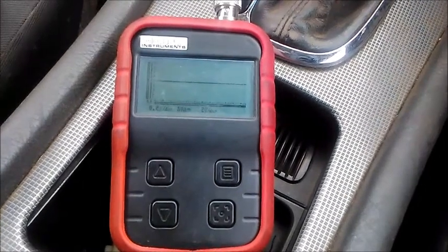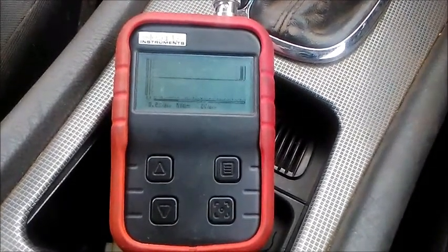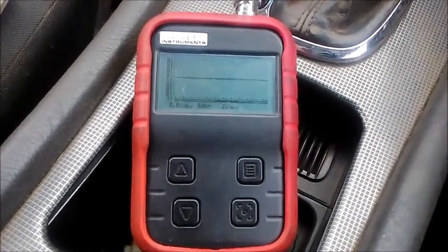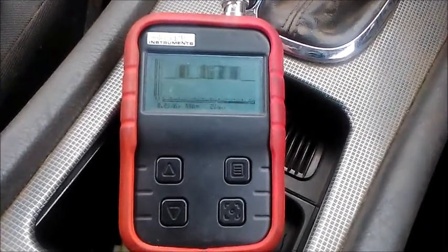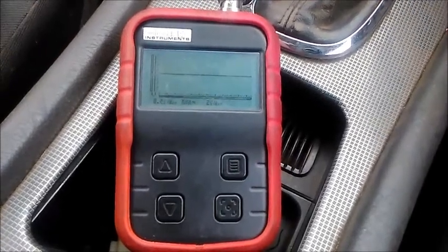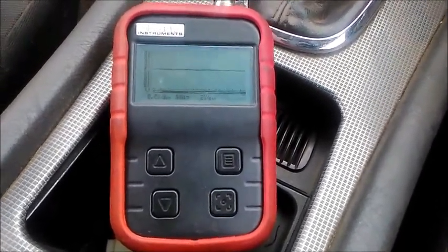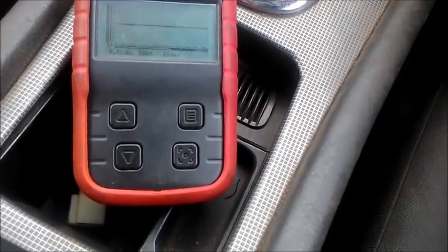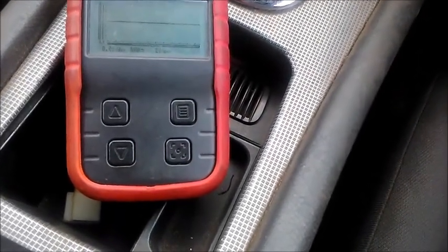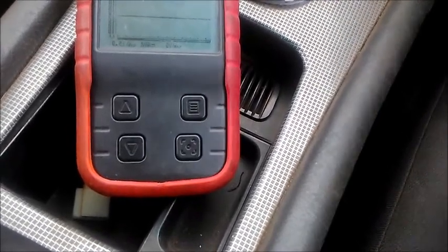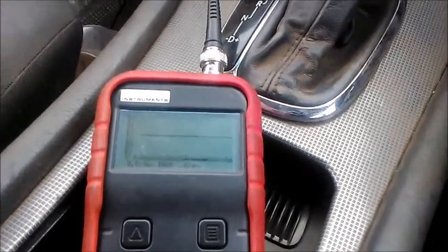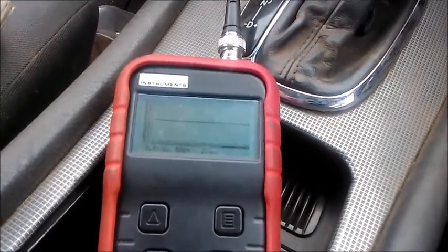I'm going to attempt it a second time and see if I'll catch it for you. Again, see that? That's more like a signal coming from the engine as it dies again. That's more like the signal I was looking for on the other wire when the vehicle is in drive, but there's nothing. So we have one bad speed sensor.